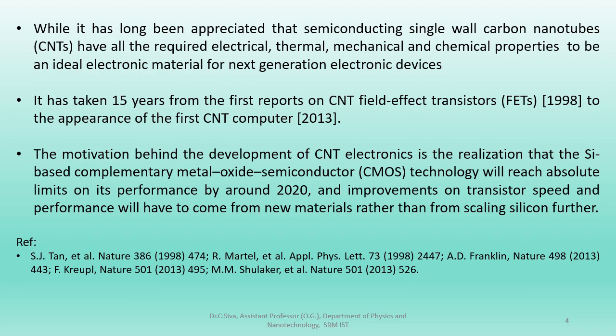Why are CNTs promising? The main reason CNTs are attractive is their extremely high mobility due to their sp2 carbon bonding. CNTs can also use wrap around gate structures, giving excellent electrostatic control.